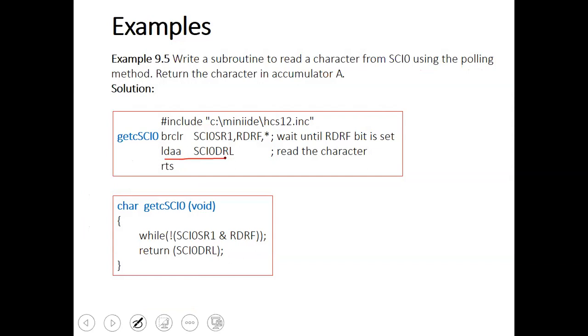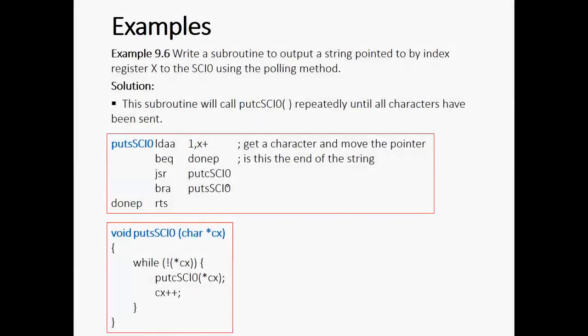You will find at the high register, the 9th received bit is stored as the most significant bit, while the 9th transmitted bit is stored as bit number 6 in the data register. The same thing here is in C, the code in C.